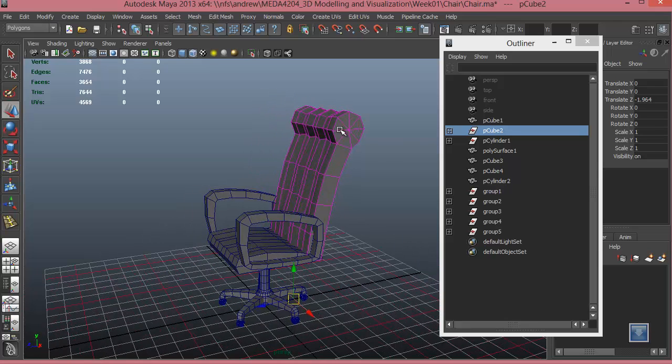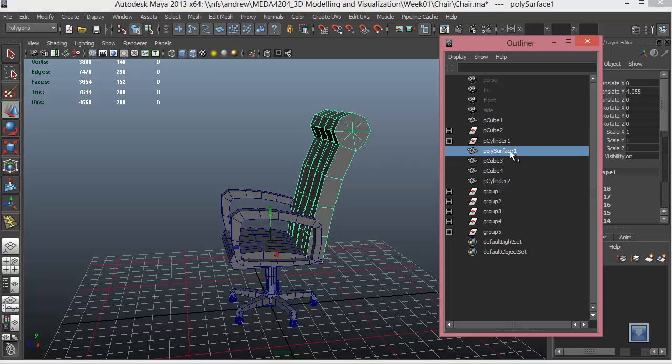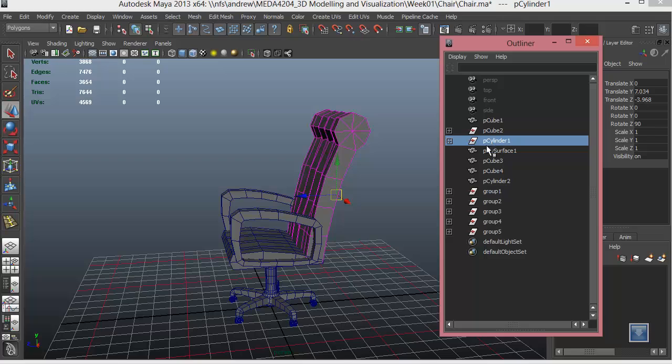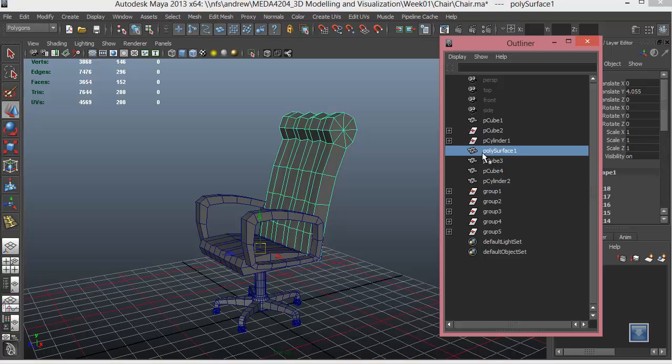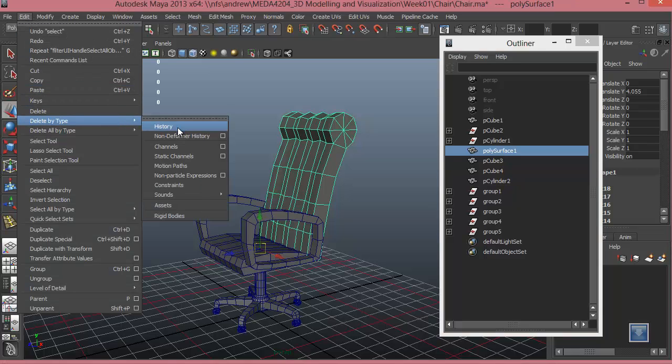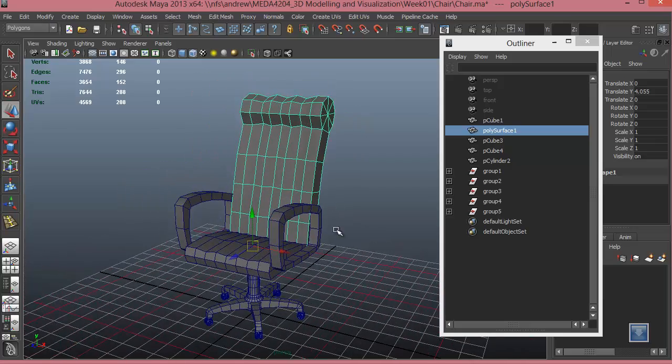Now when we combine two objects together, the shape node will get combined to form one single shape, but the transform nodes will be left alone. But they will still be connected to the mesh. That is why you see this pink color. If you want to disconnect it and permanently remove these transformations, we can select the final resulting mesh and go to Edit, Delete by Type, History. As you can see, that removes the transform nodes. So we'll have to do this for the entire mesh.